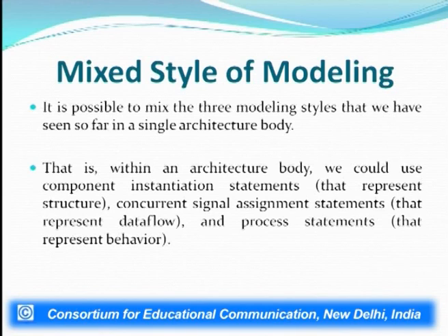Now having discussed the three styles of modeling, the next style of modeling is the mixed style of modeling. In this modeling it is possible to mix the three modeling styles that we have seen so far in a single architecture body, or either of the two can also be implemented. That is, within an architecture body we could use component instantiation statements that represent the structure, concurrent assignment statements that represent the data flow, and the behavioral process statement that represents the behavior of the entity under consideration.